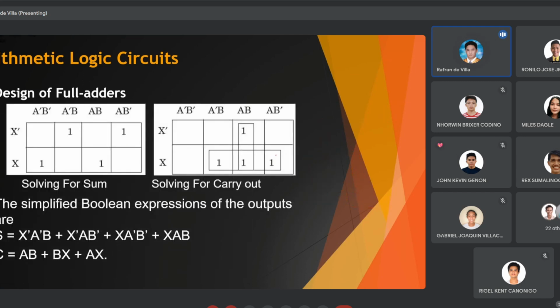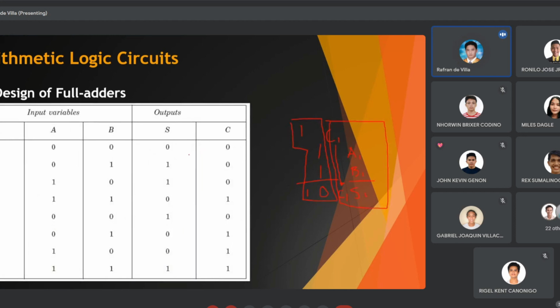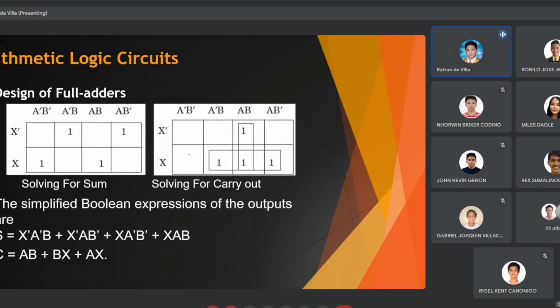So again, with this given truth table, all you can do right now is simply plot it back to the K-map for simplification. So we can see here, as we simplify using the K-map solely, you'll be given this answer. As we can see here, using K-mapping, you cannot group them because those are diagonal formations, which you cannot group since they are not adjacent.